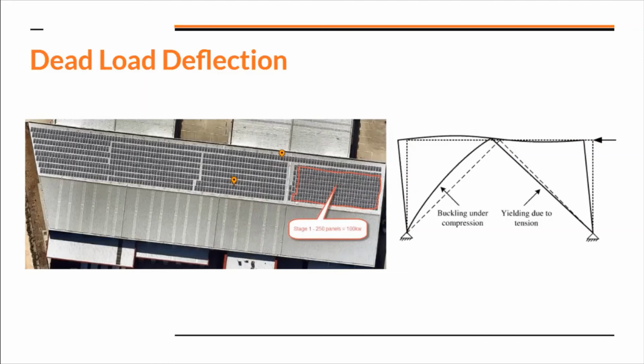What can happen is you get major deflection on your purlins, firstly, themselves, and then anything that's off the purlins. So you've got pipe work, you've got false ceilings. There's a lot of stuff that could start cracking. Your emergency fire systems will start cracking, and they start spraying water around. And it might not happen now, but it could happen in 3 years' time when a big gust of wind comes and it's major pressure, the wind's pressured onto the north side, and you've loaded that side with it. It's already towards its deflection limit, and now it's gone over.